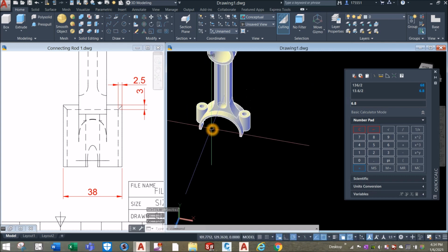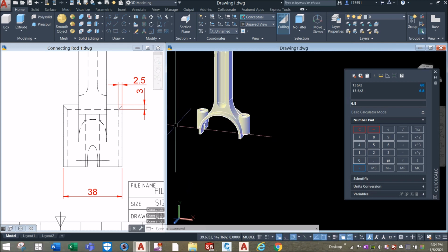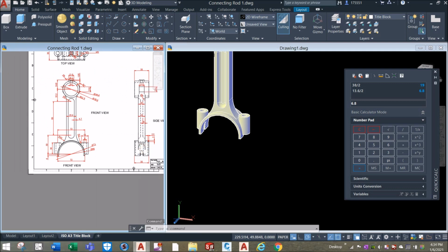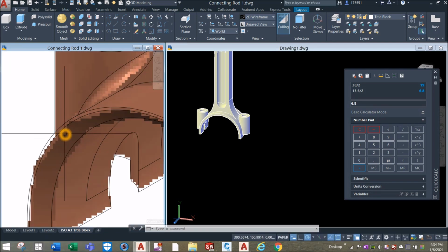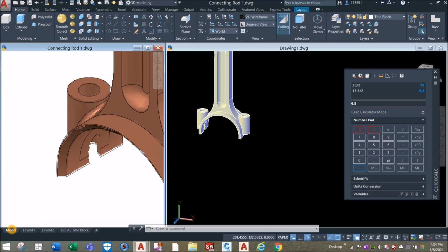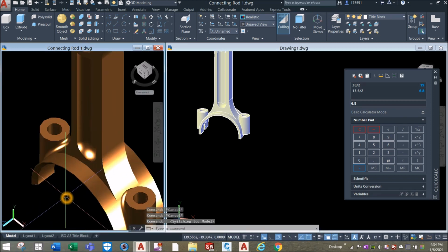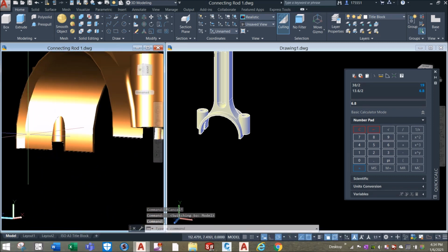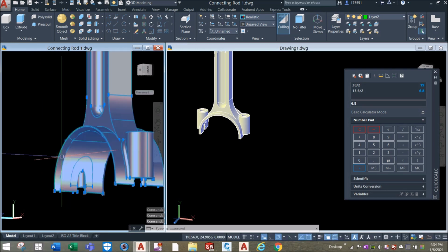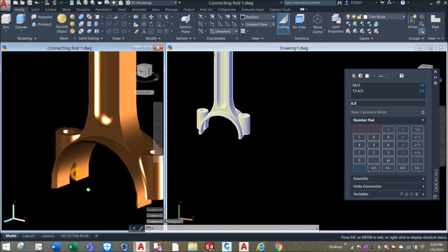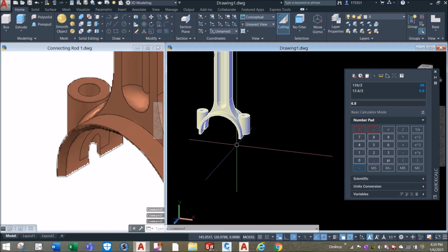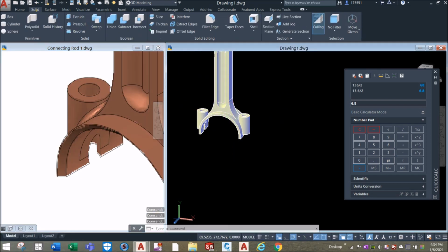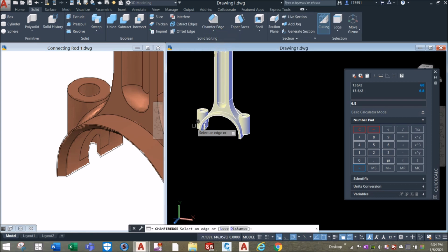All right. And the next thing to do is apply chamfer to achieve this one here. I'm going to show you the model. This one here. And go to solid and select, click this drop down arrow and select chamfer edge.